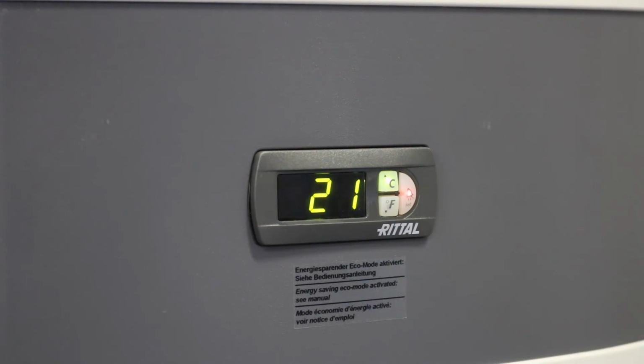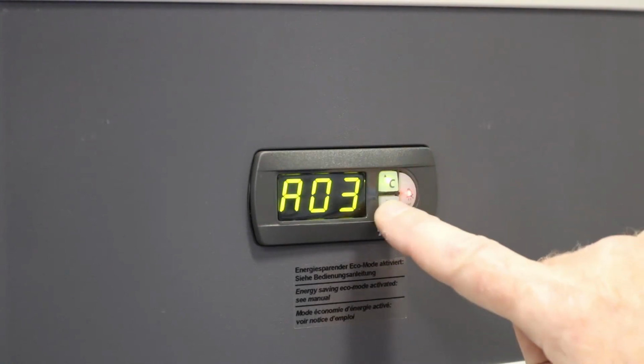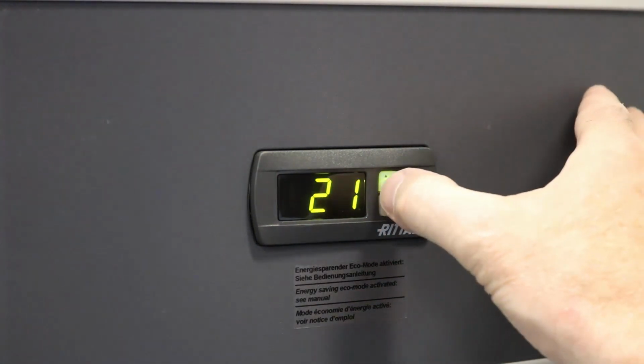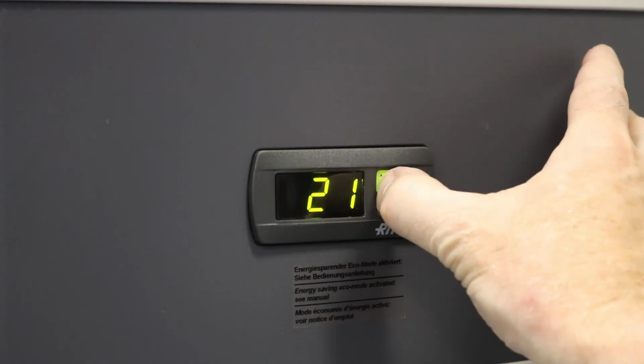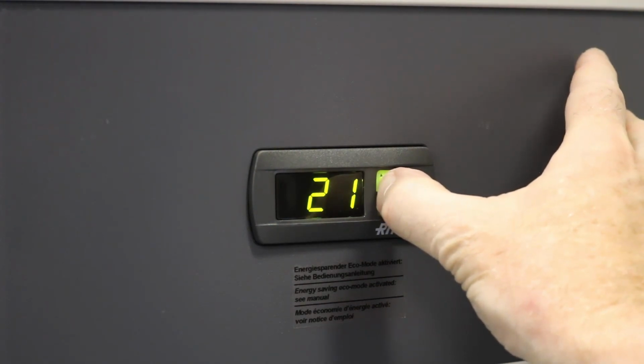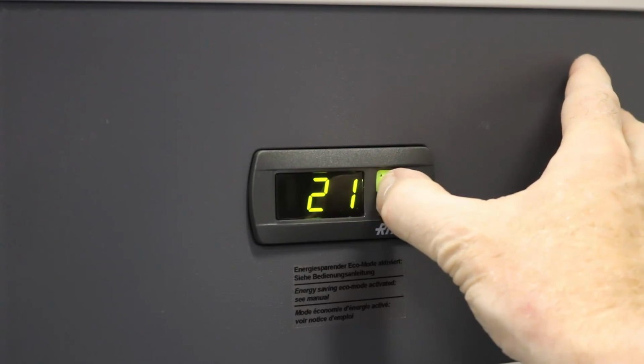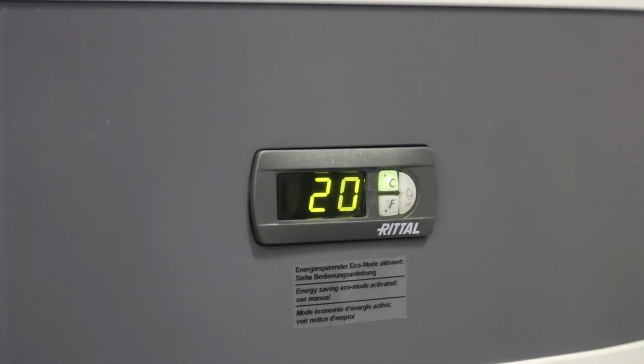Now, to clear that, you have to fix the problem. So what I've done is I've removed the filter material, okay, and then I'm going to go back in, and once you fix the problem and you want to reset or clear the message, I'm going to use the C and the F key depressed simultaneously, and then that will send it into a self-diagnostic mode. This is about a 5-minute test as it checks everything. So we've time-lapsed again, and now it has cleared the code.